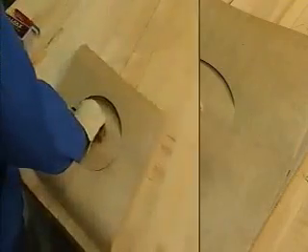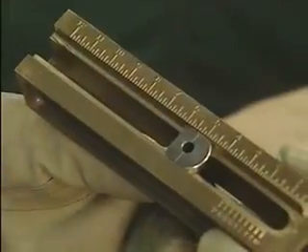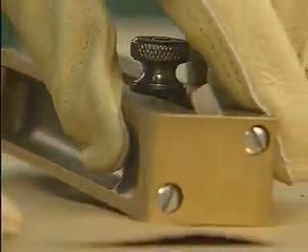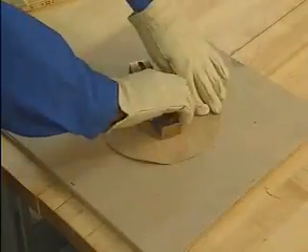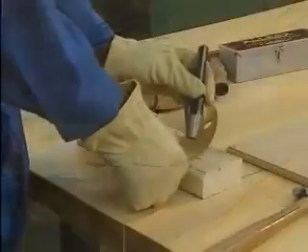The mechanic then removes the cutting tool from the pin and readjusts the blade to the inside diameter measurement of the pipe flange. He places the cutting tool back on the pin and turns it one complete circle to cut the inside edge of the gasket. When the cut is complete, the mechanic removes the tool from the pin.